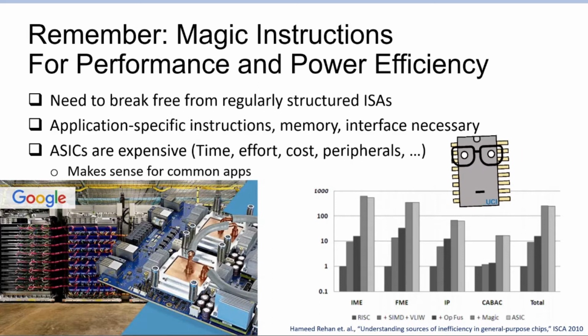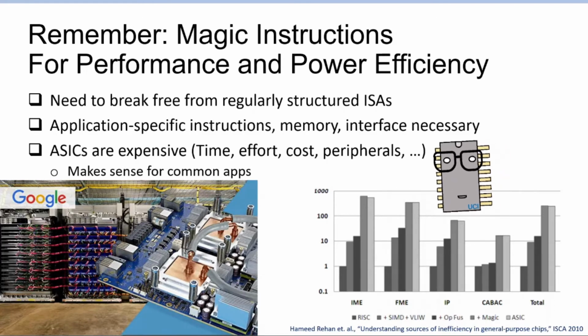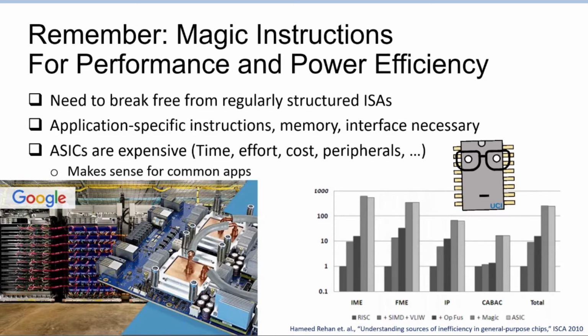And once you have a board that talks to your ASICs, that whole board also has to talk to the rest of the system, either by having an Ethernet port or a PCIe endpoint, things like that, to either plug it into a host machine or plug it into the network. So all of that incurs engineering cost, and it's not something that someone used to software engineering can jump in on overnight.